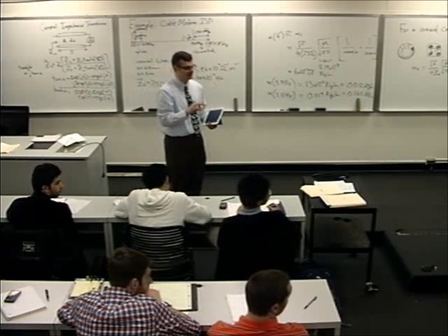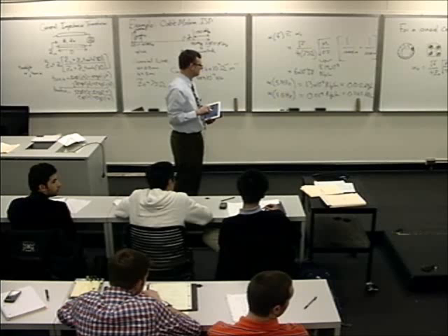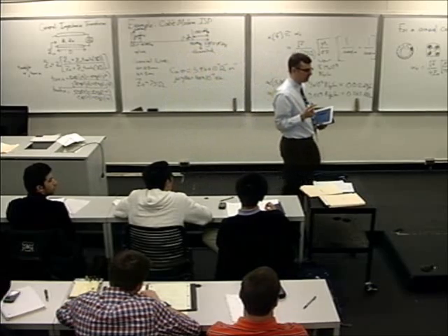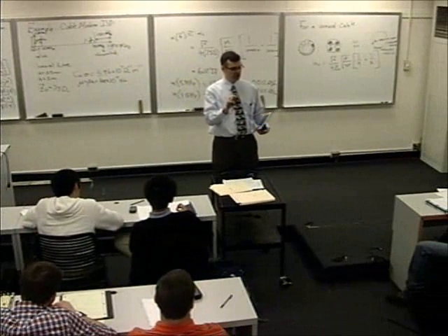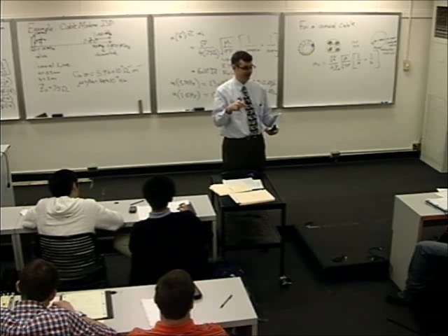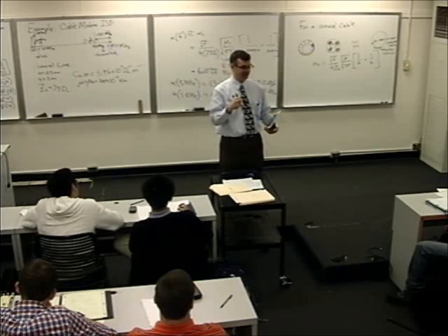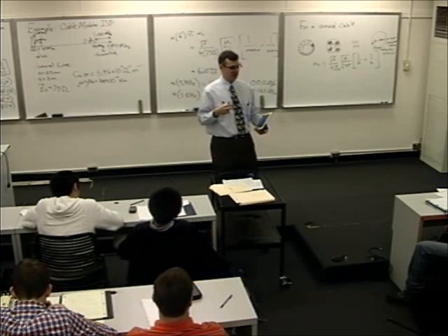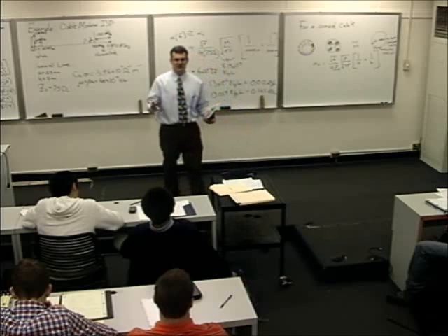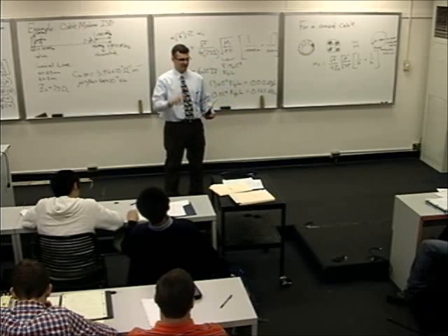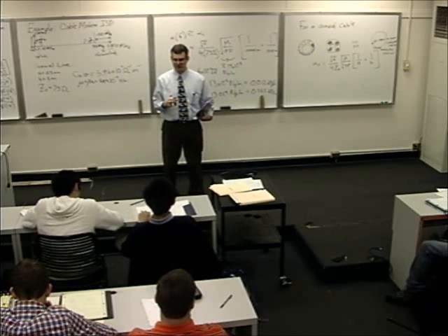Yeah, Blanca. Shouldn't the losses be negative? Because if it's dB and it's positive, it means that's higher than 100%. Yeah, so the convention is if we call this a gain, then it would be negative. If we call it a loss, then it's a positive value. So it's sort of which side of the fence you're looking on. Whenever we talk about loss, we negate the amount of attenuation.